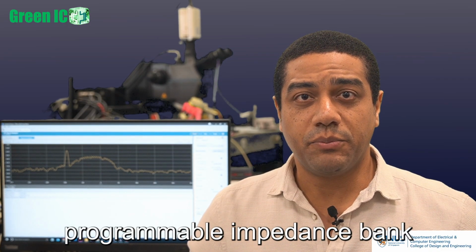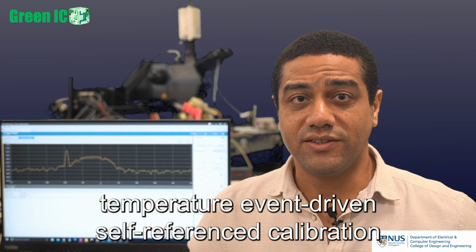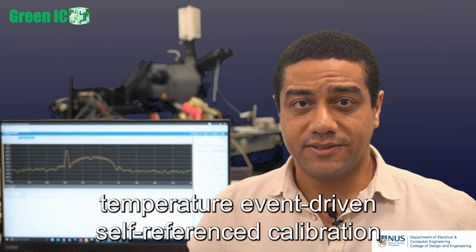Essentially, the temporal profile of the antenna reflection coefficient is updated by modifying the RF switch impedance of a programmable impedance bank at appropriate times, based on the timing set by a calibrated delay line. At each sample period, the latest 3 input bits digitally select one of the 8 complex response patterns, which in turn corresponds to a different combination of 8 basic complex loads, Z, leading to the desired reflection coefficient. The corresponding impedance is generated by the programmable impedance bank. Temperature and process variation for impedance and delay lines are compensated via a temperature event-driven self-calibrated reference.